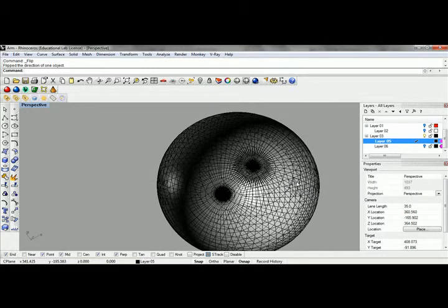It creates a big problem for us, because it thinks the rest of the universe is outside in this little area, the rest of the universe is the interior of the model, and the exterior is only the small little bubble. So it'll print a big old spool or a mess, or it won't print, or it'll print fragments. It'll basically fail your print one way or another.